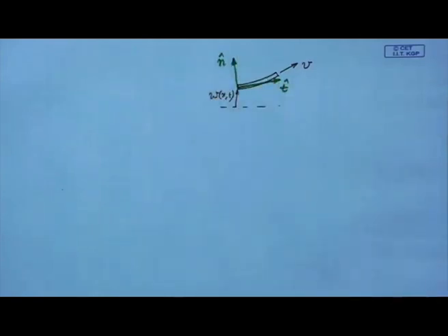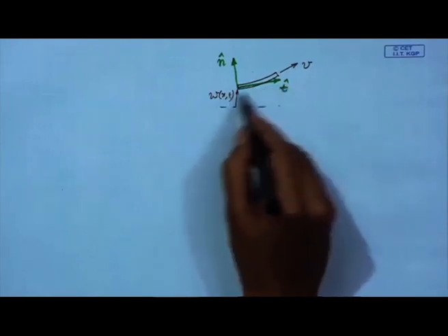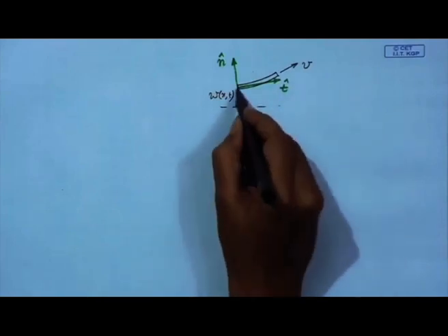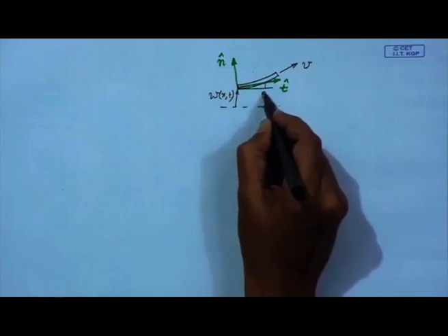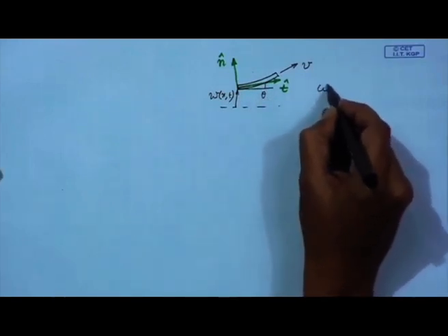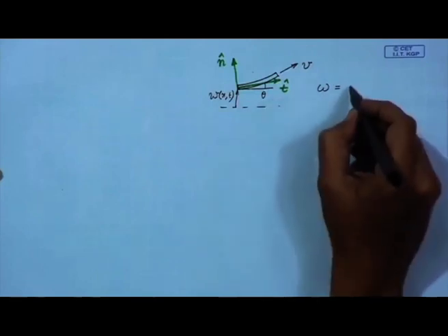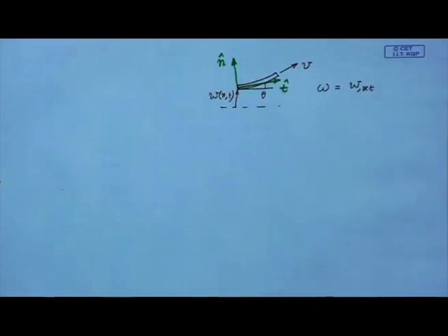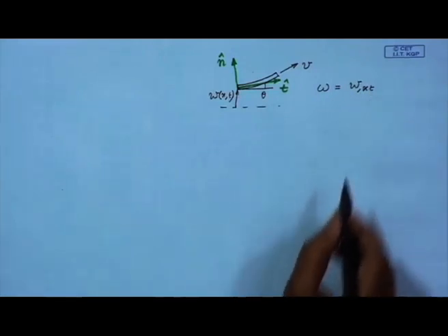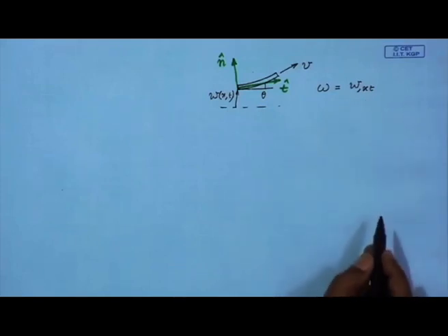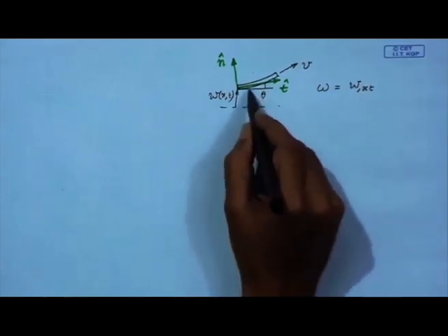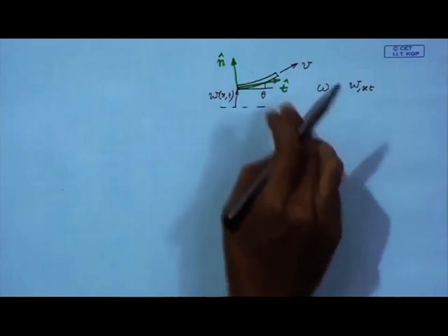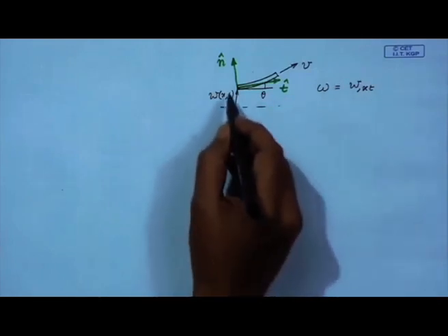with this element. So, this is the tangential direction to the string, and this is a normal. So, this frame rotates. So, this angle is theta. So, the angular velocity of this frame, let us say omega, can be written approximately as w x t. So, it is del square w del x del t. So, del w del x is nothing but this angle, and rate of change of angle gives us the angular velocity.